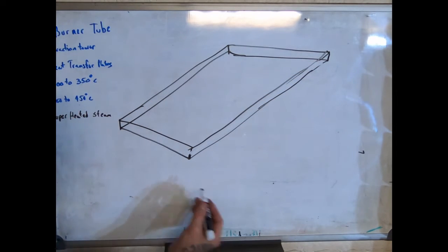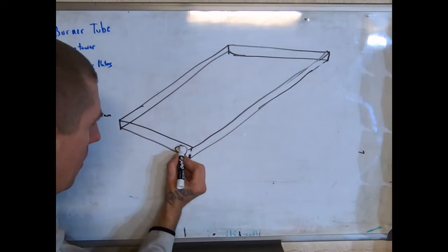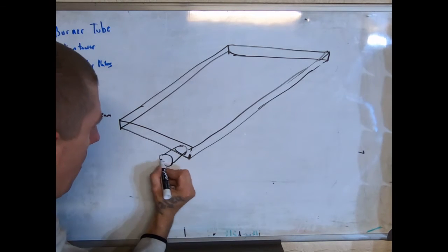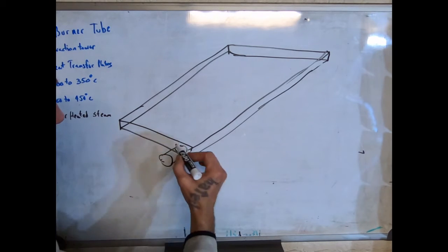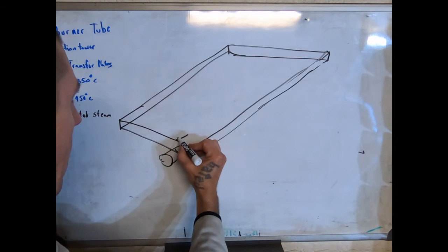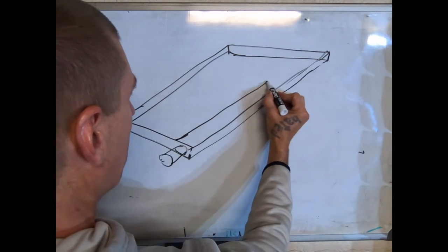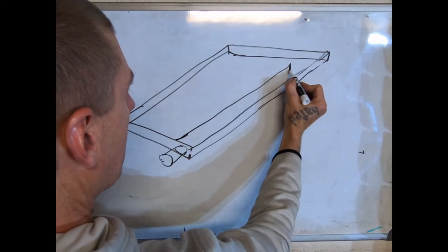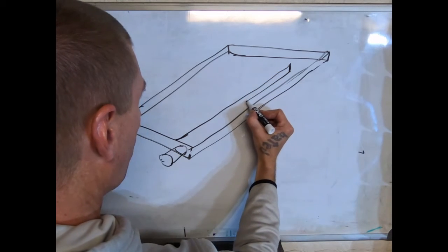And then we have an intake port here. We get our connector on there. And we would take another one of these 1.5-inch steel slats and throw it in there like this. And we would just tack weld it periodically. And we would not let it go all the way to the end.